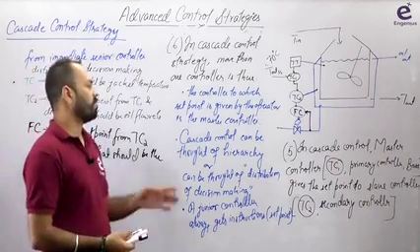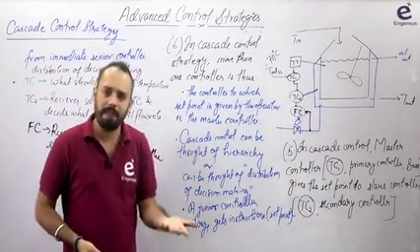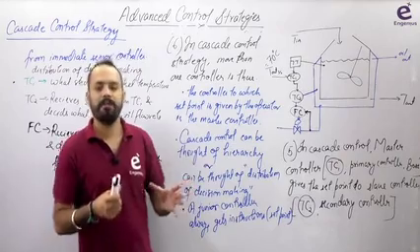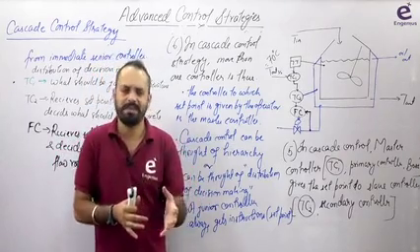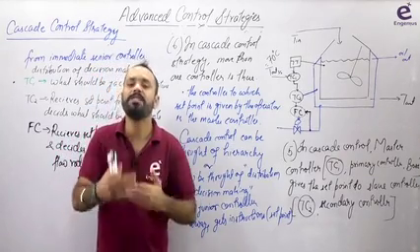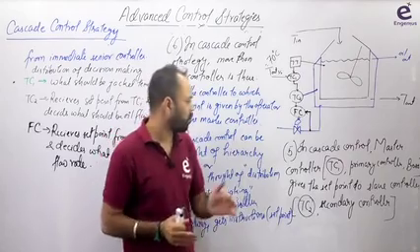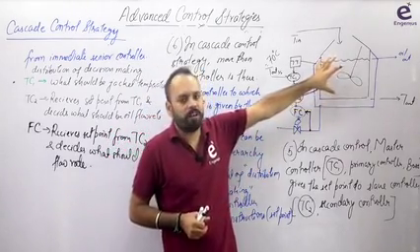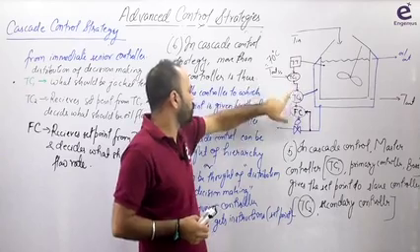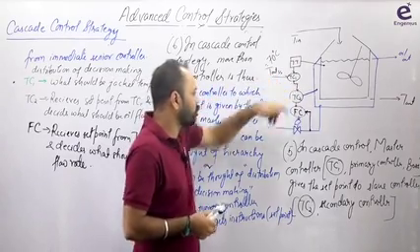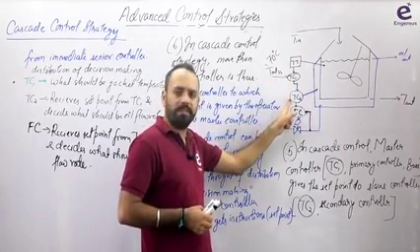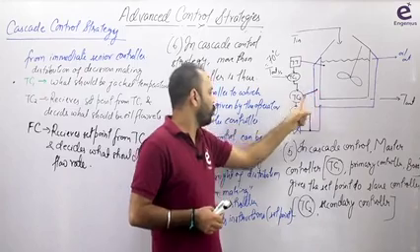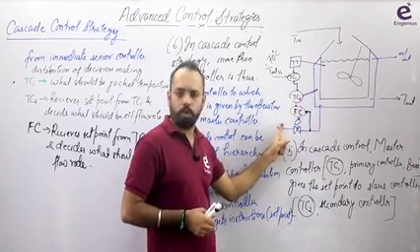Now अगर आप बोलोगे सर ठीक है, in cascading now what will be the impact? The impact will be that there will be a better means there will be more satisfactory control, fast control, sluggishness will be less. देखो सीधी सी बात है, जैसे यहां पे चेंज हुआ, आप देखो suppose for keeping this temperature at 70 degrees Celsius, what should be the jacket temperature? Jacket temperature should be 75 degrees Celsius. For 75 degrees Celsius, what should be the flow? Flow should be 8 meter cube per hour.